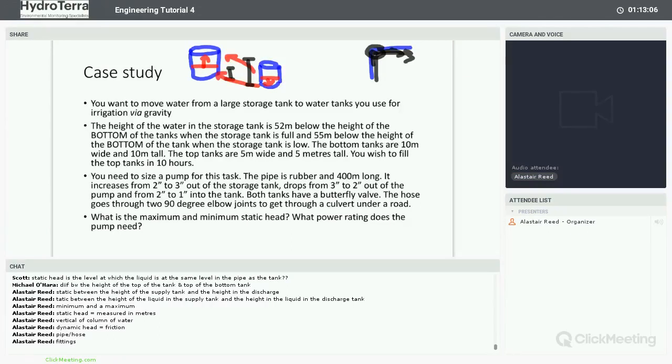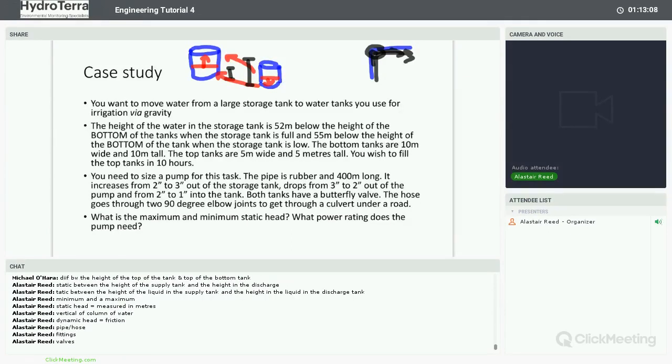If there's fittings, if they're partially closed, obviously, if there's valves, if a valve's partially closed, that will make it a lot harder for liquid to pass through them. Let's talk about fittings that reduce the diameter of a hose. So here we have, let's say, this end of a fitting is 3 inches.